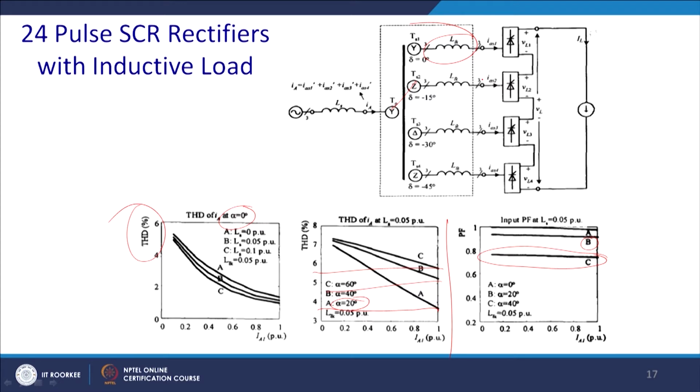That is the major corrective action you require to take at regular intervals by proper monitoring, and thus you can operate it for longer durations. Otherwise it will cause unnecessary heating of the transformer and ultimately it will go into saturation.